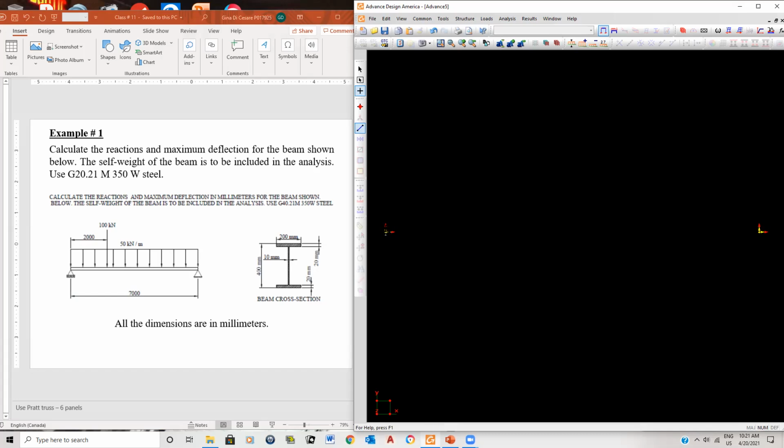Like, so once I click here, this becomes the I node, and that becomes a J node, okay? And I have 7 meters, that's great. Okay, so that 7 meters is great. Now, I can't do anything else at this point. I've got to go and assign the cross-sectional properties, because once I do that, then my model is complete, and then I move on to my loads, okay?